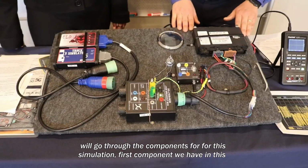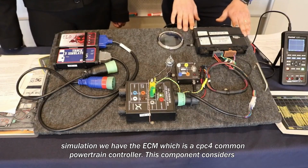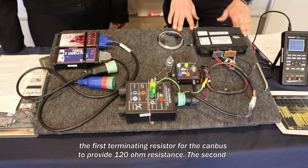The first component in this simulation is the ECM, which is the CPC4, Common Powertrain Controller. This component acts as the first terminating resistor for the CAN bus, providing 120 ohm resistance.